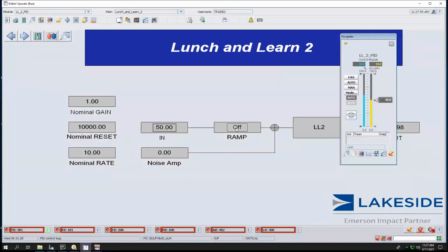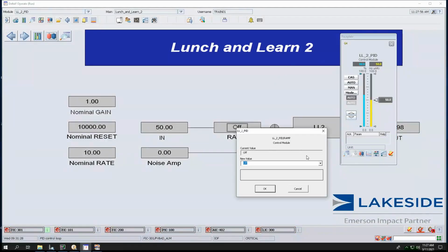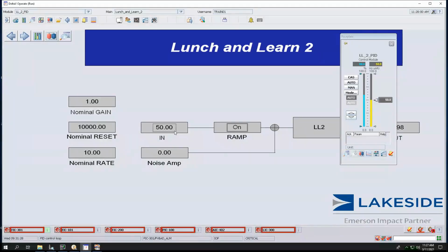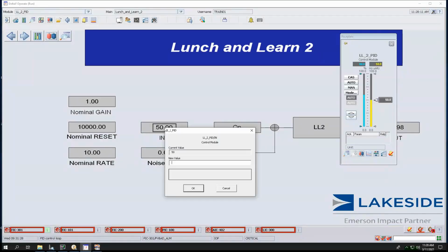So now what I'm going to do is introduce a ramp. Now when I make a change here, it's going to be passed through a rate limiter. So the error is going to change progressively, and you'll see derivative acting on that growing error. But after ramping is done, you will have no more derivative action because the error is steady.